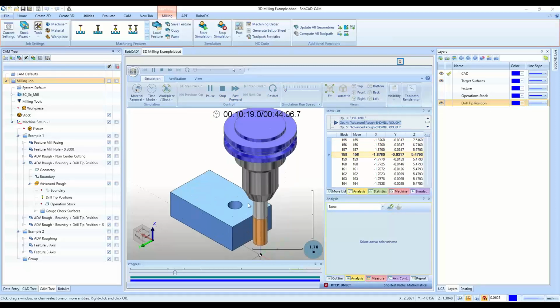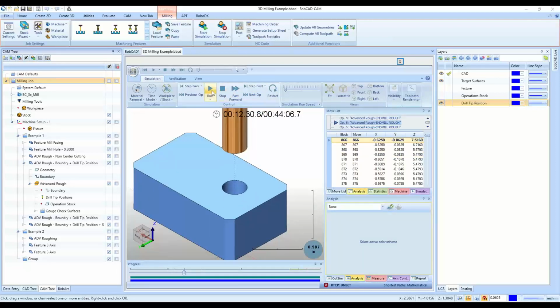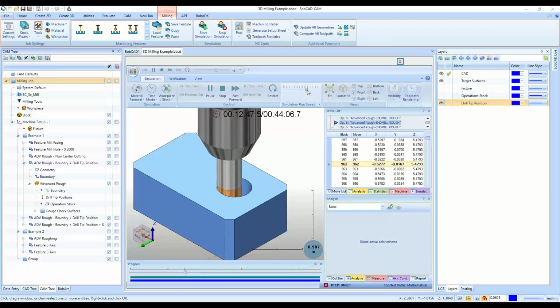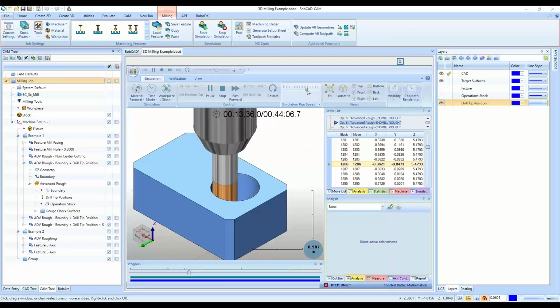This is right after this outside roughing. This is right where we start at the drilled hole location, run it, and then work our way in and use the side of the tool instead of using the bottom of the tool at all for this operation here. That's the best benefit for the